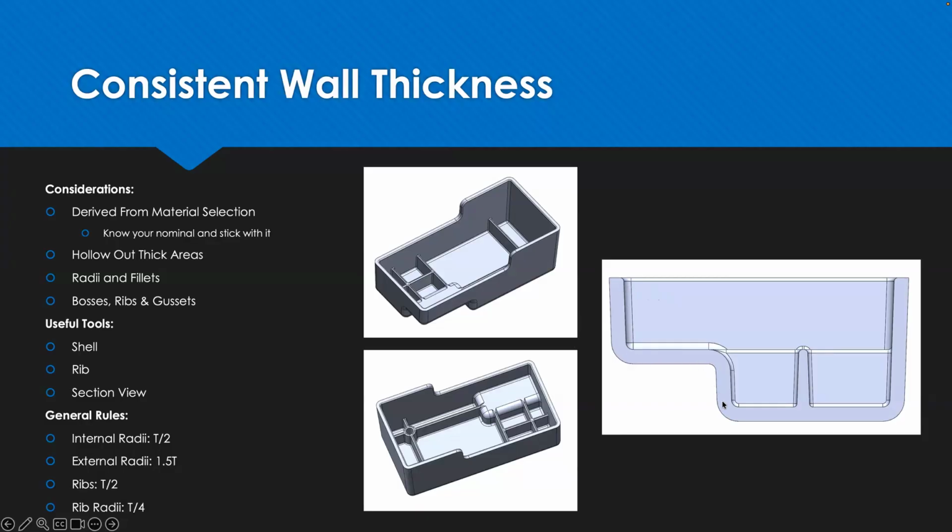But we have a very consistent wall thickness. You want matching radii, which I'll touch on. And the places where you'll see the thickness change are for good reasons as well. Things like these ribs. Actually, sorry, no, we do touch on this in this slide.